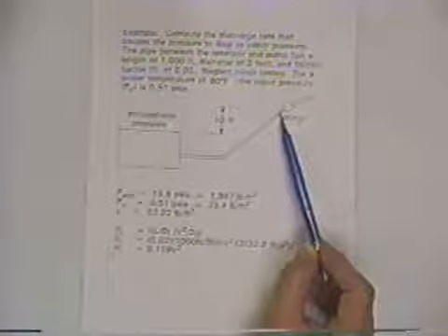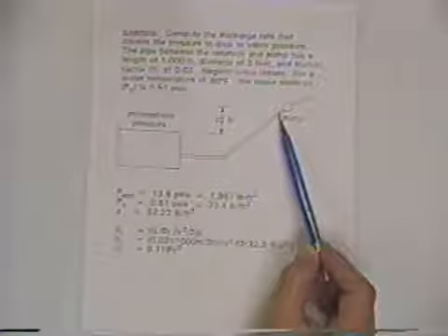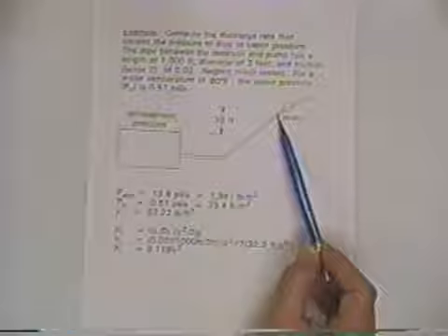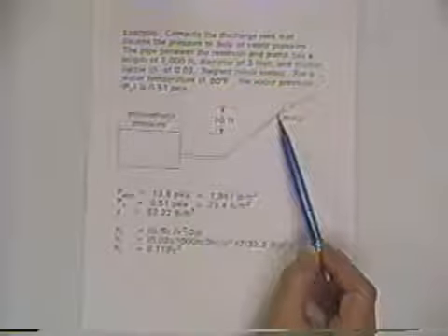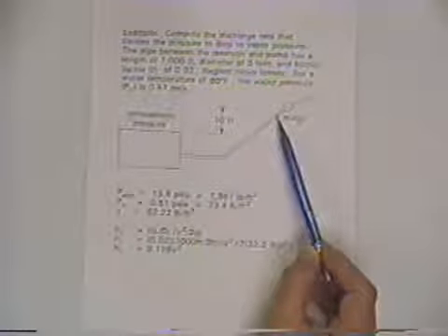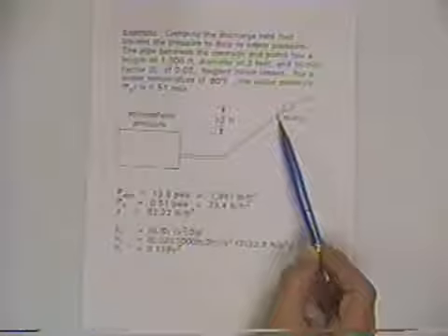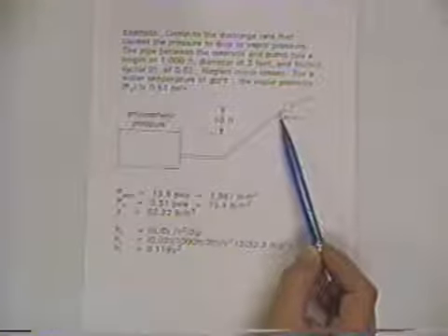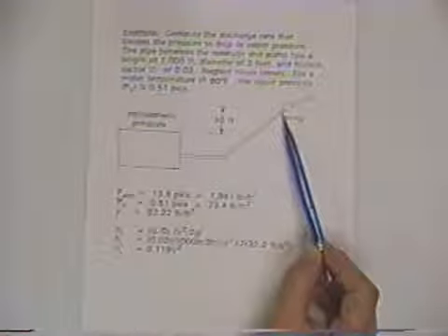But even before you get to absolute zero, practically what happens is, if you get down to vapor pressure, that's when the liquid water starts making bubbles of gaseous vapor. And then those bubbles can implode, and a problem called cavitation occurs. And you can actually do destruction to the pipe and to the pumping system and so forth.